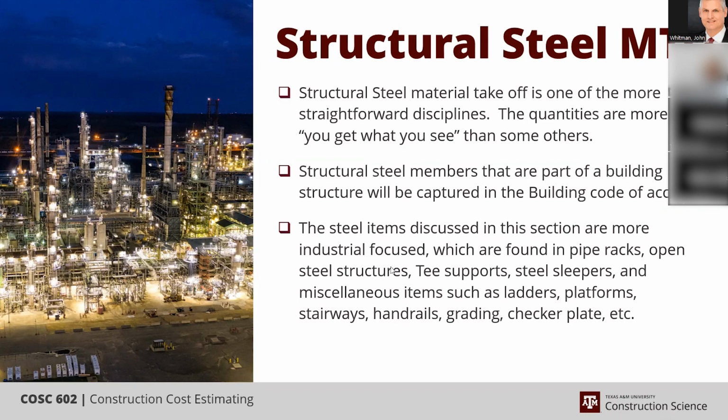But if you don't put it in the concrete and you account for it in your quantities, you're doing the exact same thing. You've just approached it in a different area, and that's legitimate. The main thing is that you know where you did it, and I know where I did it, and the next person knows where they did it, so we know we've got it covered and it's not forgotten. Yeah, it's just a little bit easier for us for tech stop bids that are timed. We have to squeeze a lot of them in at one time, so sometimes it's easier just to add a waste factor than create a whole new item in HeavyBid.